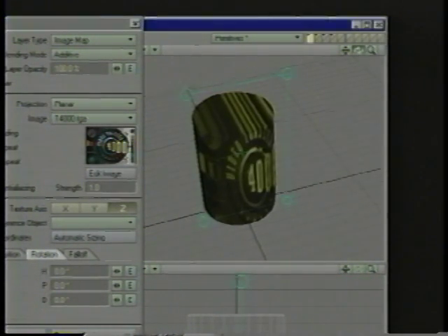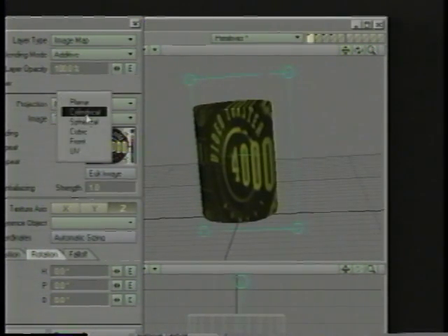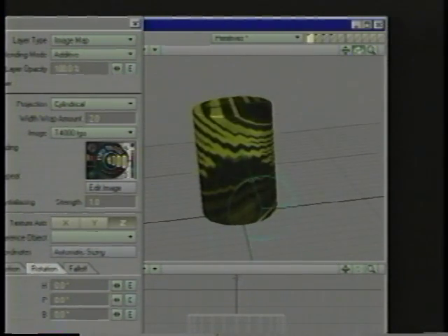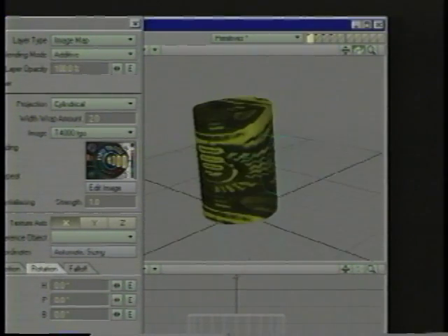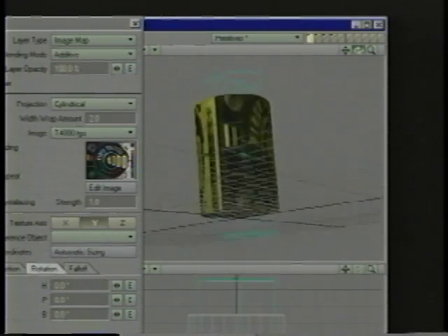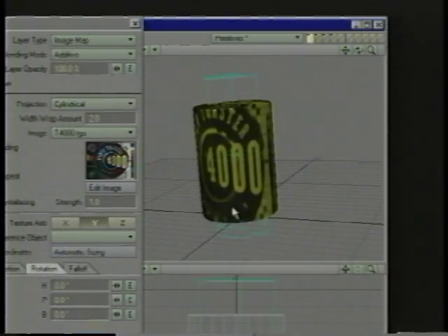Now again, because this is a cylinder object, we know that we probably want to use a cylindrical projection. So we go here. And again, you'll notice that that's the completely wrong axis. So let's do an experiment. Is it X? Nope, that looks wrong also. How about Y? And there it is. You can see now the cylinder matching the cylinder widget on the same axis.